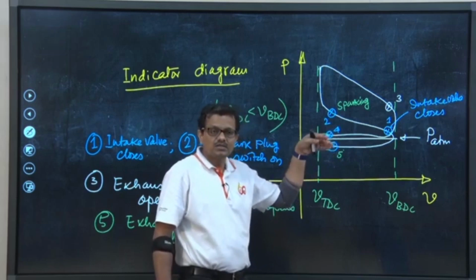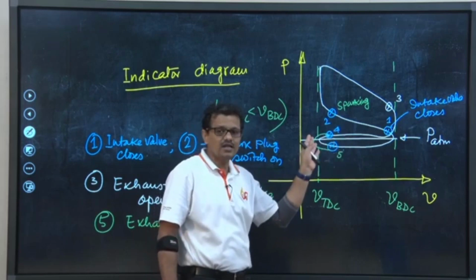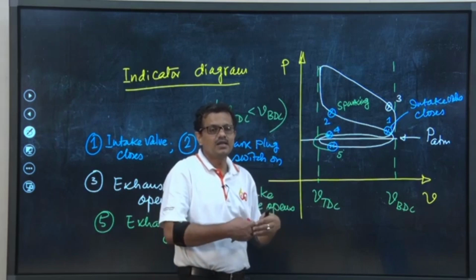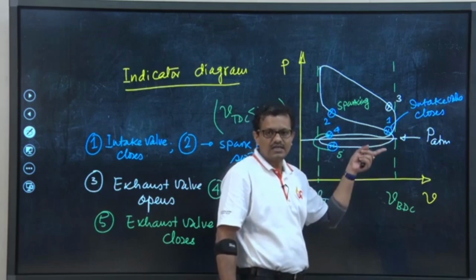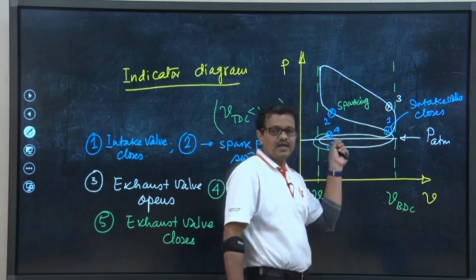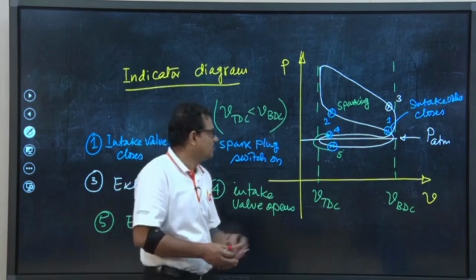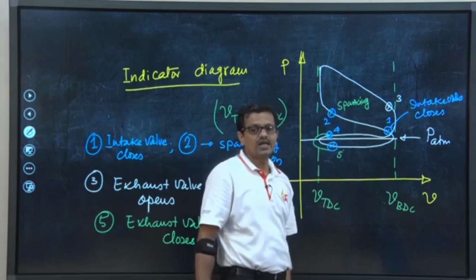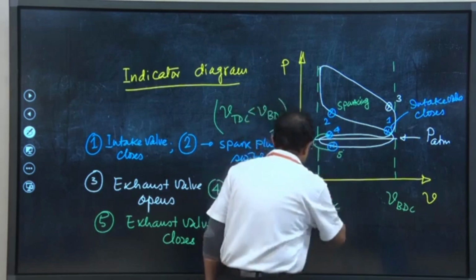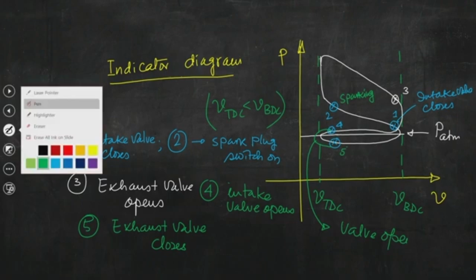But the diagram that we have drawn today is for the 4 stroke cycle engines, and we can see that we have mapped several processes to complete a cycle of a 4 stroke cycle engine, and from there we have understood several timings of valve opening, both intake and exhaust valves. We have also identified an interesting point that there is a regime in which both valves are remaining open, and this particular zone is known as valve overlapping.